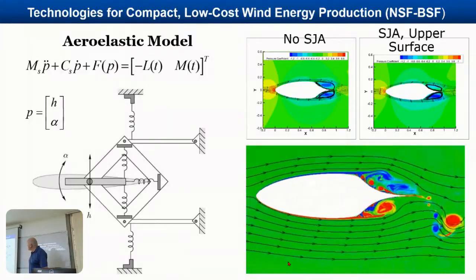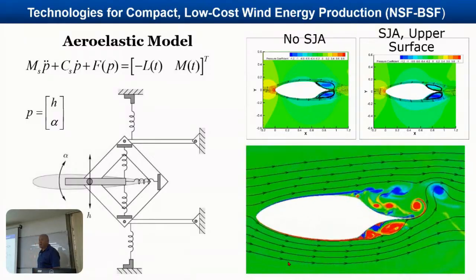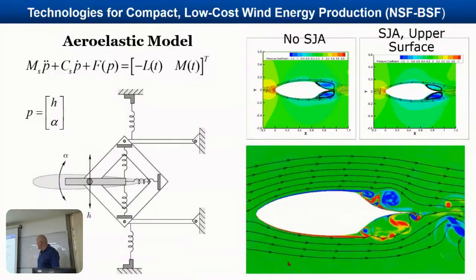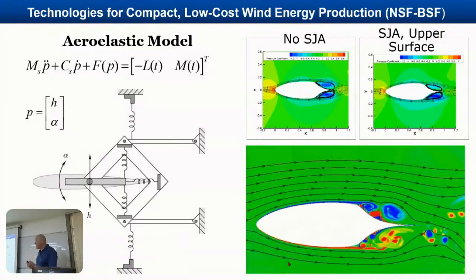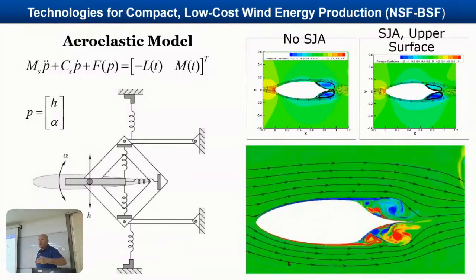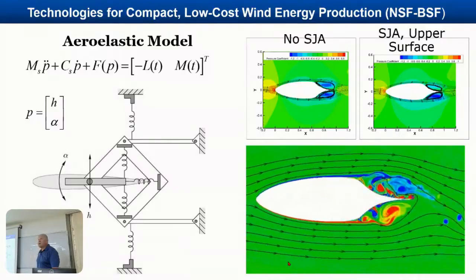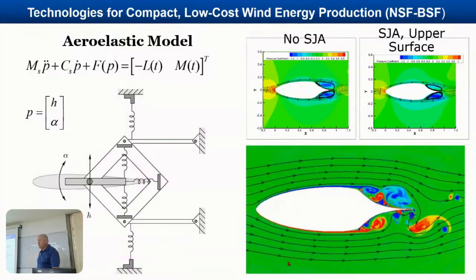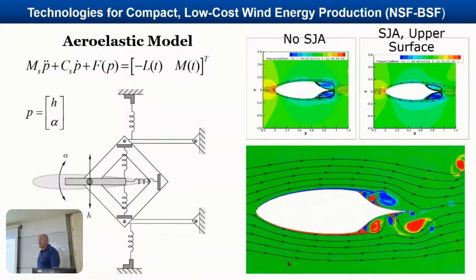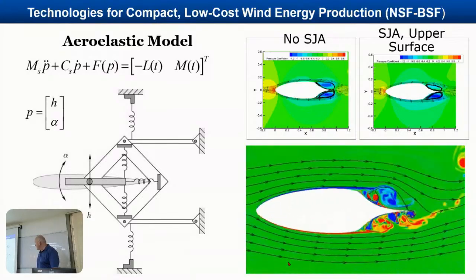So the idea for us is actually to have this new geometry, because again, if you have this kind of geometry like here, NACA 0012 or something like that, 0010, that's what the experiments were done for the flutter, which were validated against. So our original model was validated against experiments, which was done, of course, for the regular NACA 0010 airfoil at the Royal Institute of Technology in Stockholm, Sweden, and they did a very careful analysis for this, what they call LCO.